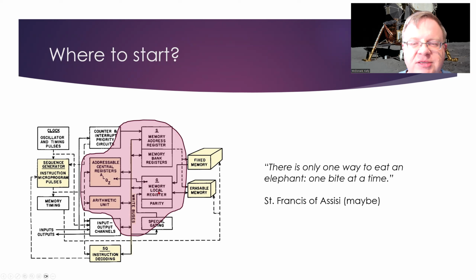There's also some interesting, not control, but logical operations that the G register can provide. It does some shift register left and right, depending on what's needed with the data that's coming back. And then there's parity. This is not something we need to be as concerned about with the replica that we're building. Parity is really a way of checking the contents of memory, as it's read in and read back out, to make sure there are no memory errors.